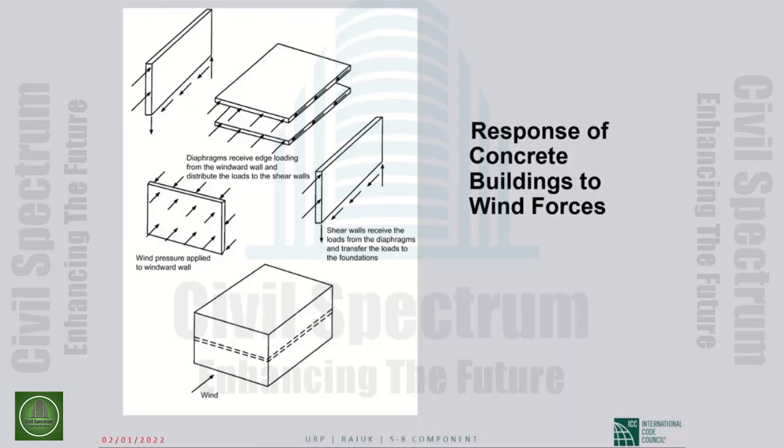Most concrete buildings are simple diaphragm buildings. The masonry buildings also can be many times. Wood buildings probably are not most of the time. So anyway, a simple diaphragm building is where the wind is transferred from the point of application down to the ground via the floor and the roof diaphragms. Okay.